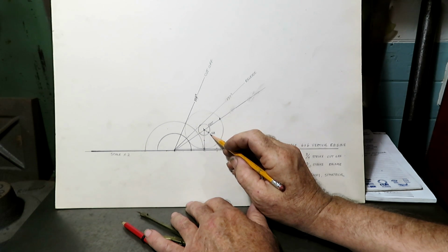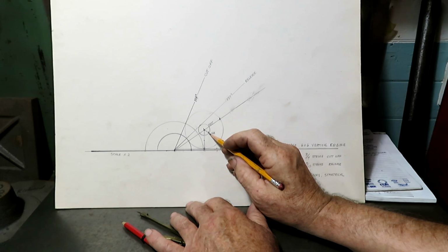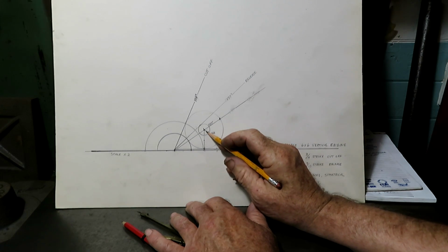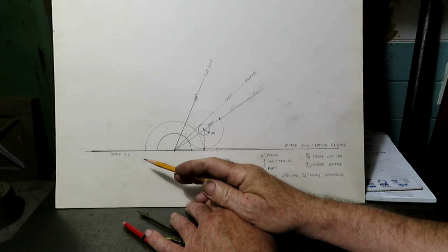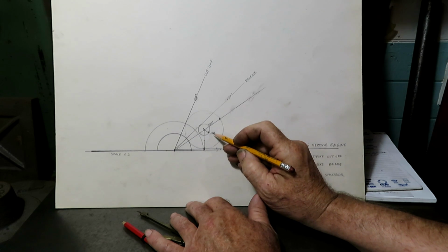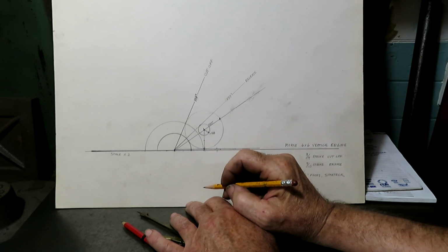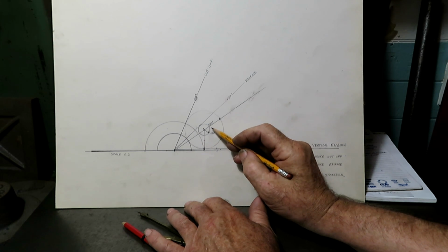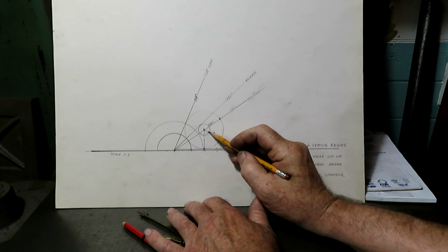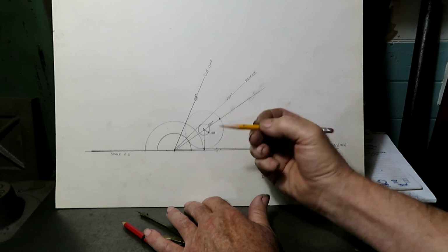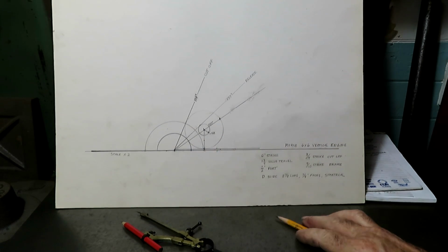The radius of that circle is directly measured to be the inside lap of the exhaust cavity on the back side of the exhaust valve. And after dividing this dimension here by 2, because we're at a ×2 scale, it was 0.168 inches. And so that'll help us figure out where that exhaust line is going to be on the back side of the D-slide valve.